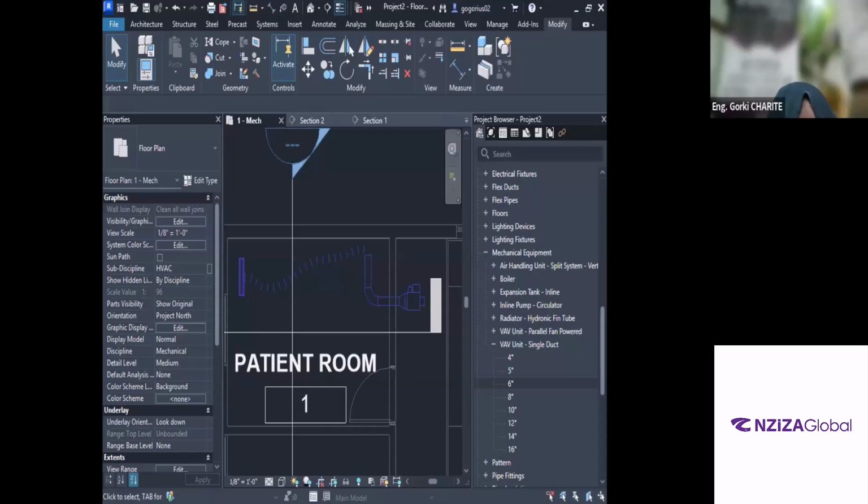Okay. All right. Now we have connected our terminal, the air terminal diffuser to a flex duct. Flex duct is connected to a rigid duct. Rigid duct is connected to a VAV box. Just like that, one by one, we are going to go backwards all the way up to the central air handler that we discussed first day and second day. Is that making sense? For that, we require that E20 spreadsheet. For each and every room that we are using, we require that E20 spreadsheet so that all of this calculation can be done. Is that making sense? Yes.